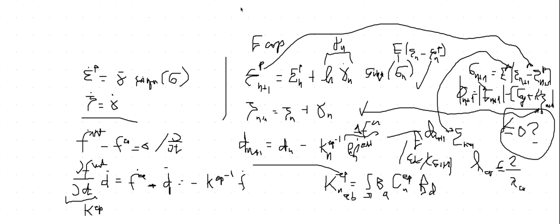So this is related to this tangent stiffness matrix. But in the case of plasticity, it's not enough to worry only about that. You have to worry about the time step, which makes P negative or 0. So what we're advocating in the book of Owen and Hinton is basically reducing the time step. So you're sure that not only you have stability, but you also have this plastic admissibility of the stress, which